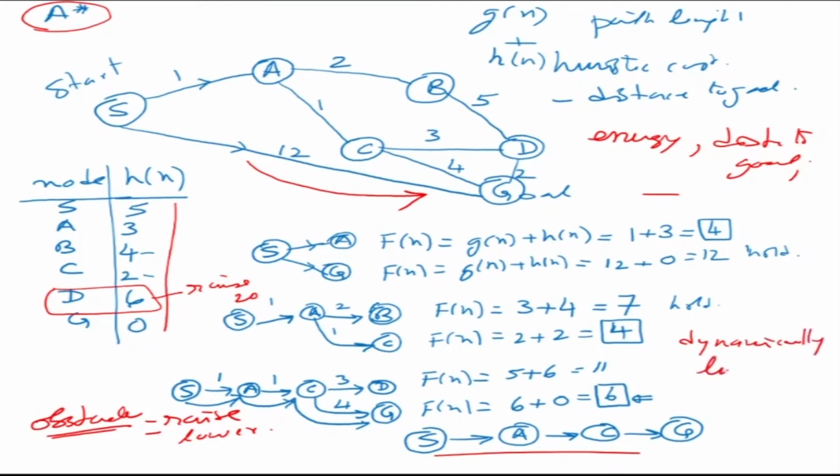the values of the heuristic Hn, and this is what we call dynamic A star, or D star. So we looked at blind search, then Dijkstra's algorithm, then A star. Now D star, or dynamic A star, is exactly the same as A star, the only difference being that you can raise or lower those weights as you go along, so the robot doesn't get stuck somewhere. If there's an obstacle, the robot understands that there's an obstacle there now.